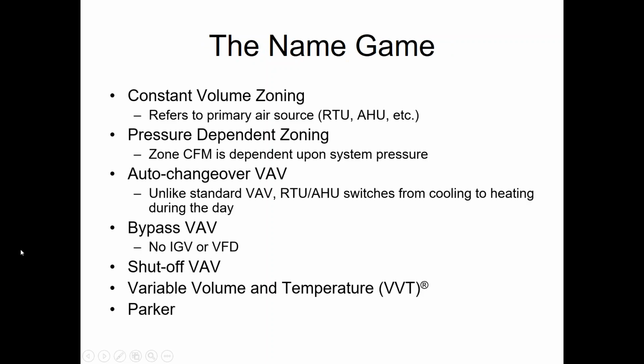If you guys have questions, type them in as we go. I see I got one from Mike. So Mike is saying, is pressure independent more popular than pressure dependent? As a general statement, if we go by quantities of zone dampers in the industry, yes, there are more pressure independent zone dampers in the industry, meaning VAV systems.